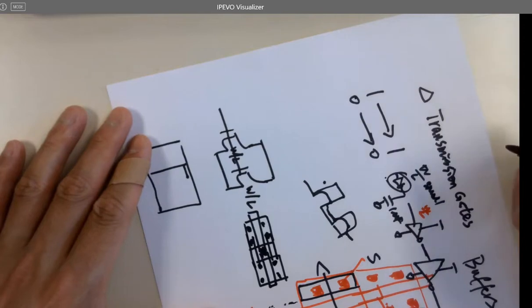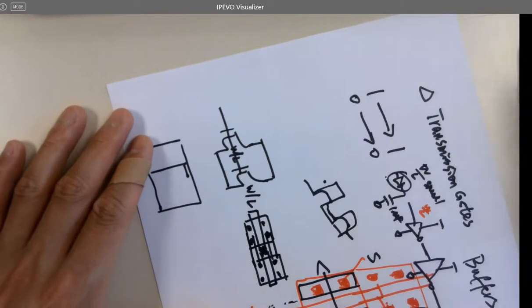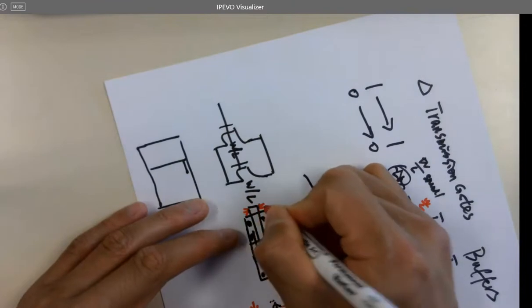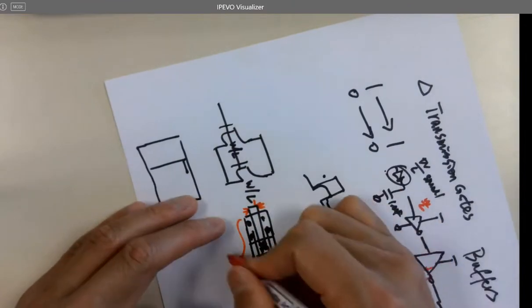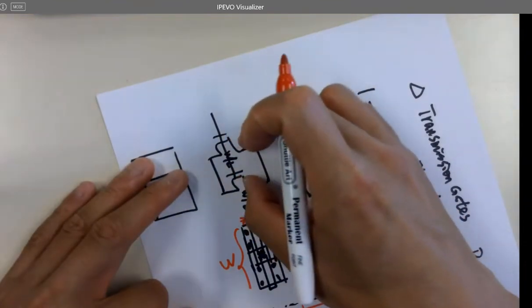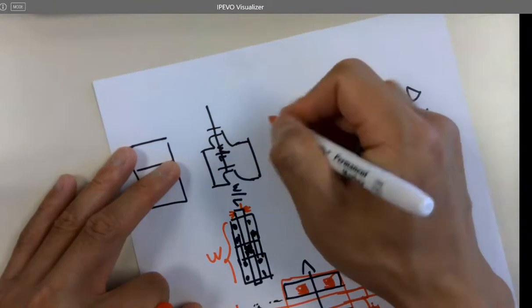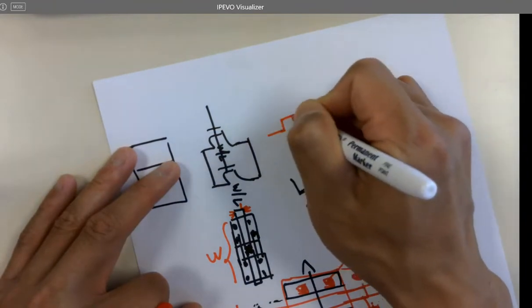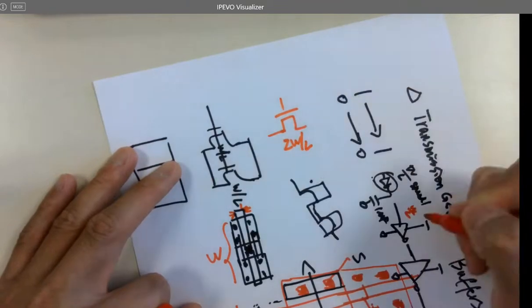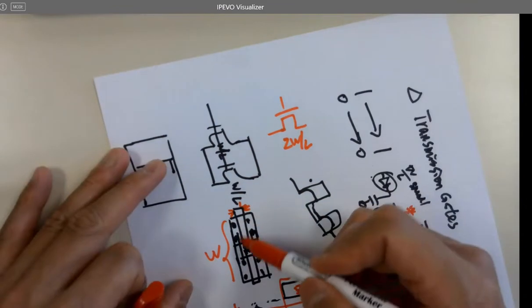Do you have a wider one or longer one? No, wider. Remember which one determines the length of the channel? The gate. So I have a bigger W here, right? So if you have two transistors being shorted to each other like that, it's equivalent to one transistor, but with 2W over L. Same performance. So a lot of times you can simplify the transistor in that way.